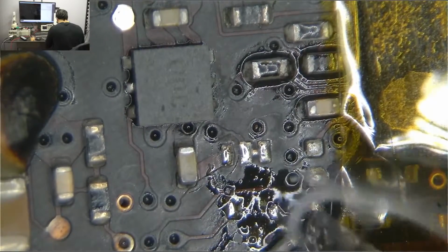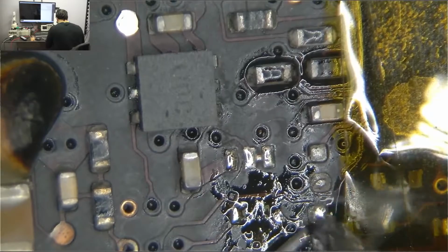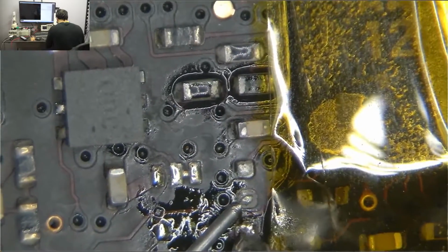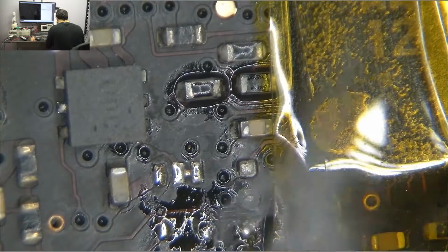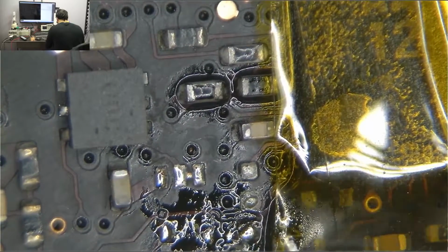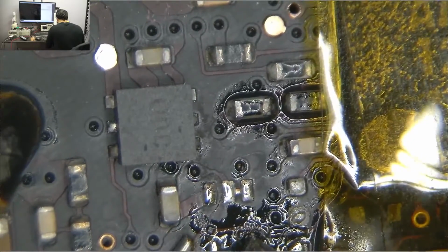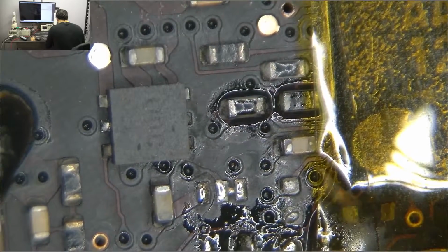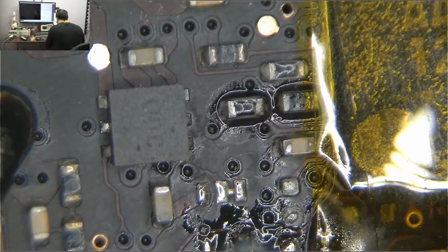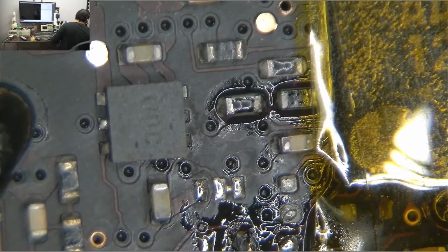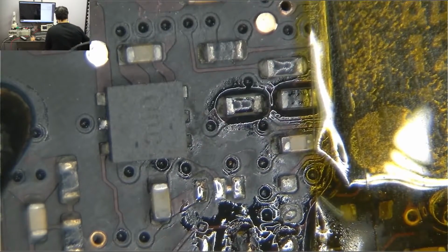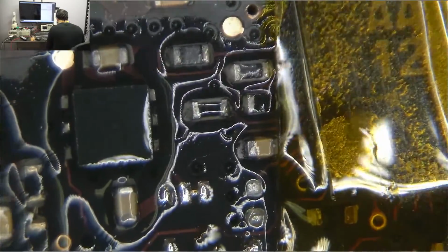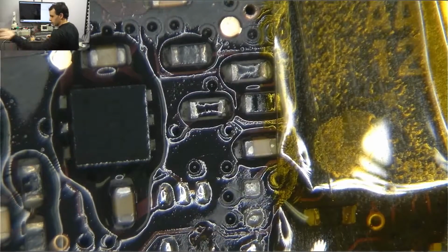We're just going to etch away a little bit of the copper on the board. See what I'm doing here? I'm trying to etch away at the copper on the board so I can make space to put some solder. See that? Now we're going to do the same over here. Sometimes it's just totally burnt and there really is nothing you can do, but sometimes it isn't. On the pad for the capacitor, the etching worked. On the other one, there's nothing I can do. So we're going to put that new component on there, and then we're going to go from there.